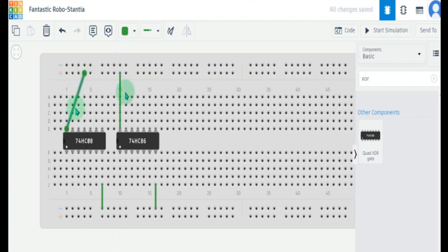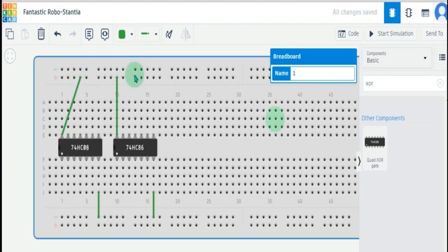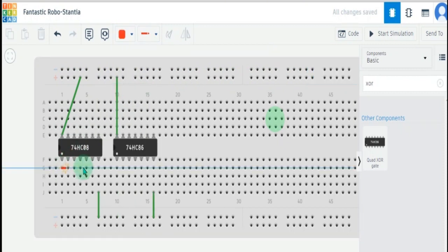Now let's connect it. As we know, both the inputs A and B are connected to both the OR gate and AND gate ICs. So let's connect this line to this line and this line to these lines, which means now if we apply any logic level to this line and this line, this will also apply to here and here, which means if we apply any logic level to the AND gate IC, it will also apply to the OR gate IC.